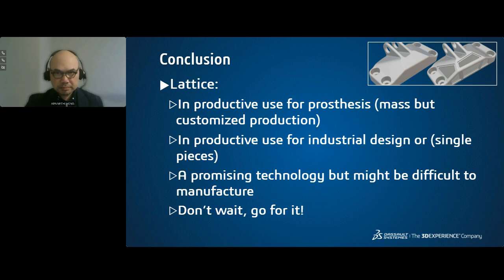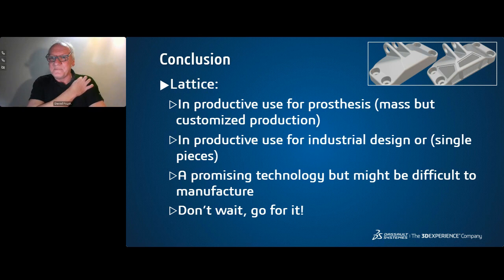Yeah, I fully agree. By the way, it's not that easy to compute a good shell mesh of a TPMS in contact with the outer body, which is a tetrahedral mesh, and have a consistent, very valid finite element model. It's not easy, but we took particular attention to get the result properly solved. That's right. Okay. Perfect.